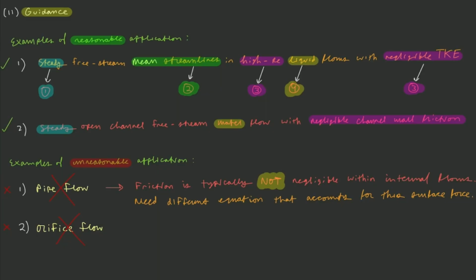What that's saying is it is physically impossible to get 5 liters per minute out of that orifice with that pressure differential, because that is the amount of flow you'd get with no friction, and no system is frictionless. Adding friction to the system will reduce the flow you get for a given pressure differential. So in that case, you would just know that this orifice and this pressure differential is physically impossible in terms of getting the flow I need. So it can give you a theoretical maximum, and that indicates I need to change the orifice, I need to increase the pressure differential, etc.